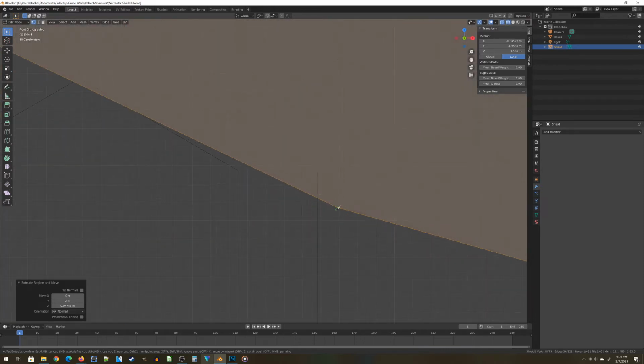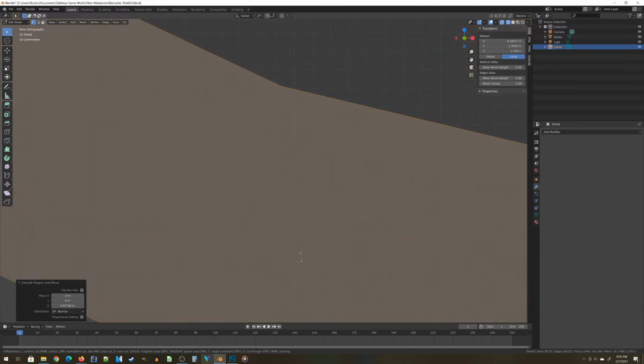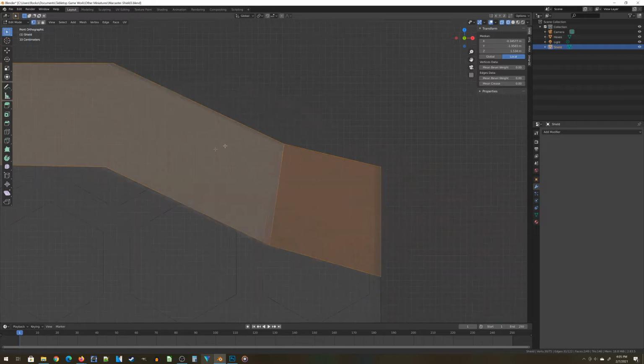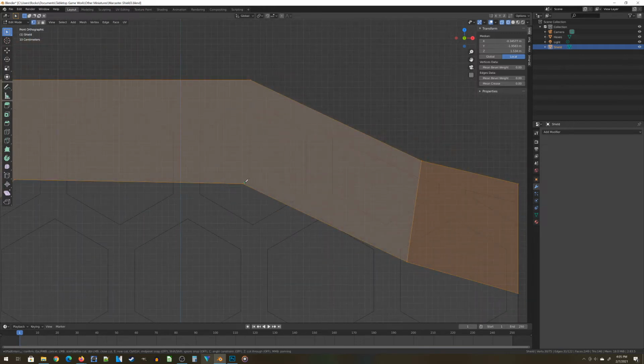So if I zoom in here, you'll notice the knife tool will kind of lock to a vertice. So I want to left click when it's locked onto that vertice, and then left click again when it's locked on to the matching opposite vertice. Then just hit enter, and I've created a line from there to there. So carry this process around for each of these sets of vertices.